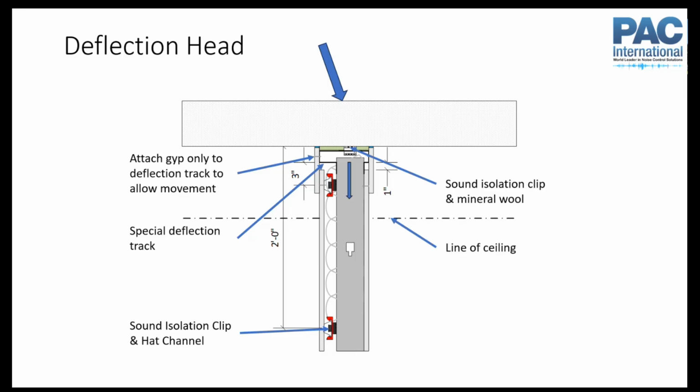But if you want to do more because you're going for very high levels of sound isolation, then you can use an isolated track. So you use an acoustic isolator, usually a rubber isolator at that track. Then you create this rubber isolation between your ceiling assembly and your wall assembly, so you reduce that particular transmission path. But you need to make sure you're paying attention again to a cavity path. So we'll typically have fiberglass or mineral wool, sometimes for fire, in the gap between the floor and the track created by that isolator.